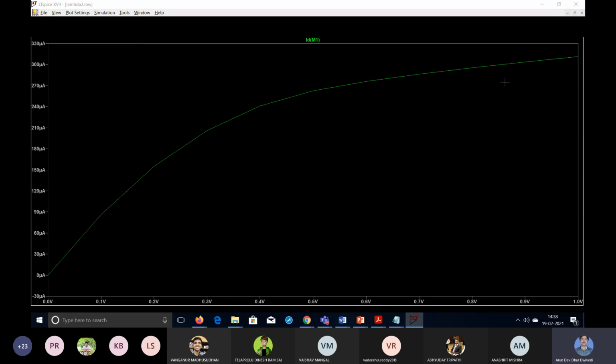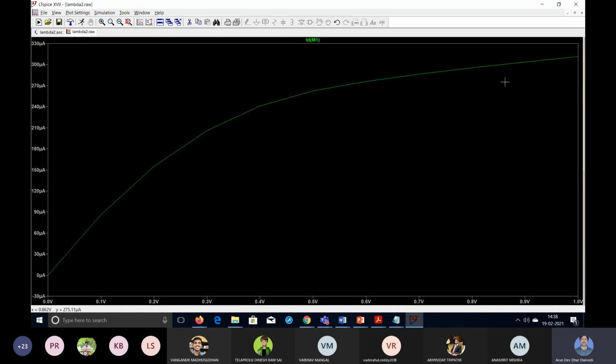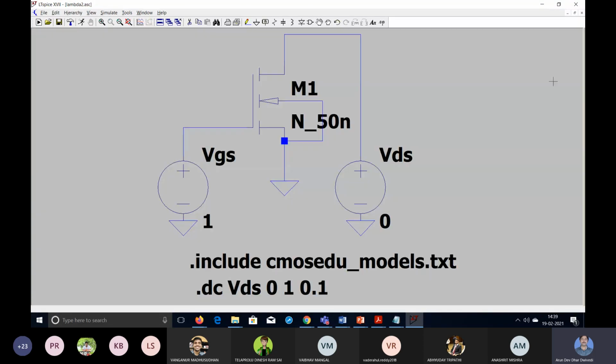We have two columns. One column is giving the voltage, the other is giving current. So at which voltage, what is the current, exactly we are knowing. So accordingly, by choosing two values of current in this saturation region and taking the ratio of them, we are able to find out the channel length modulation parameter lambda. So it's fine. Now we can move to the PMOS demonstration. I will stop here, or if you want to make the circuit, you can make it.